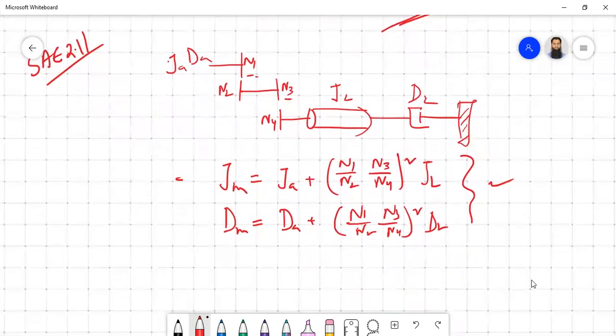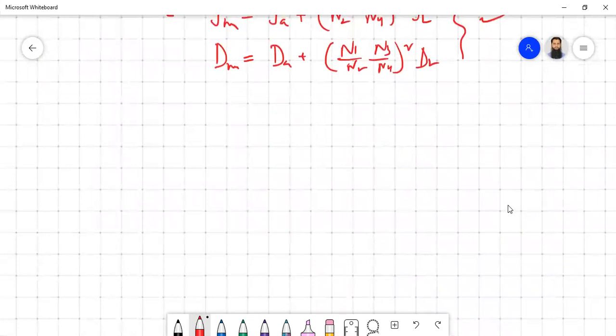And the other thing that has been given is, instead of giving the curve, they have given the equation of the load and the speed, torque and your angular velocity. So basically, they have given this equation, tau m equal to minus 8 omega m plus 200.